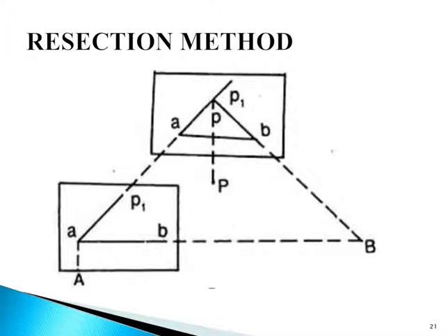The table is shifted and centered in such a way that p1 is just over P. So p1 is here, and we have to set up P as the station. It is then oriented by backsighting the ranging rod at A. Here is the station point, and we have to backsight station A. Then, with the alidade touching small b, the ranging rod at B is bisected and a ray is drawn.